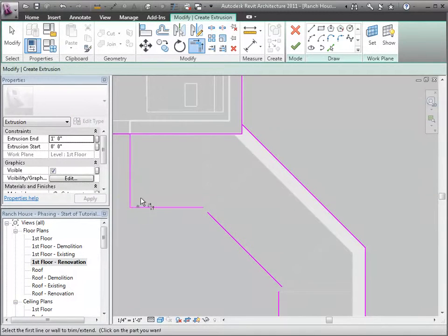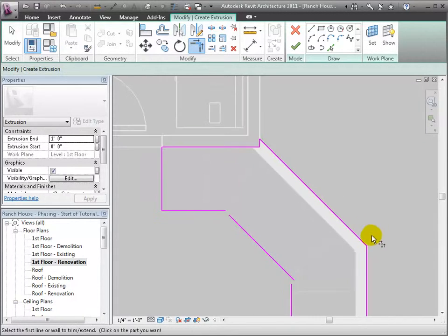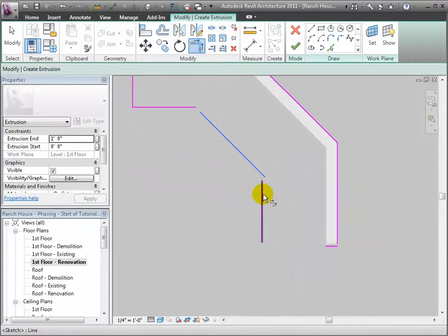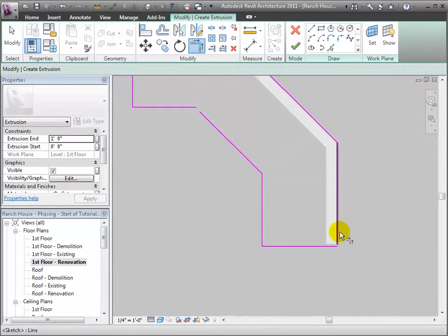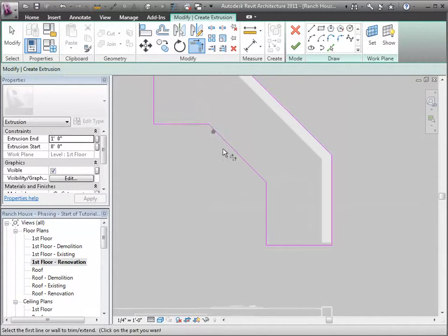TR is the shortcut. I pick the closest ends of the line that stay, to connect up gaps and trim excess line, and make a clean loop that's closed and has no overlaps.